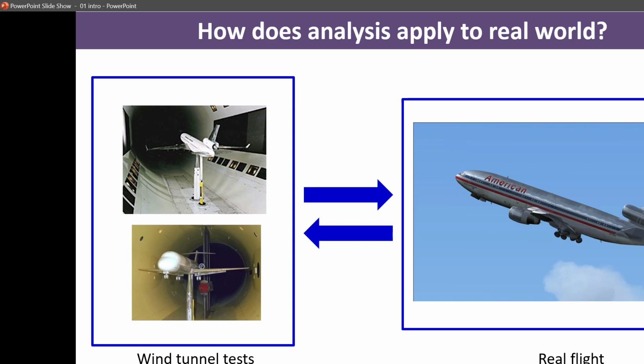That's where the flow similarity comes into play and all of the dimensionless parameters. The idea is we introduce these dimensionless parameters that we did talk about a little bit. We talked about the Reynolds number and the Mach number. These parameters are dimensionless by definition, meaning that the dimensions of the aircraft, the dimensions of your control volume, whatever that is, is not going to be important.